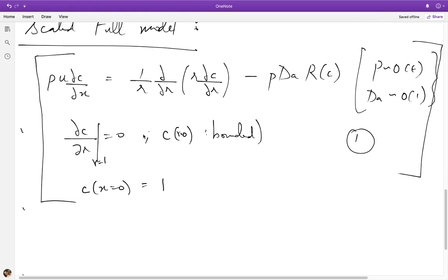Okay, so now we are in a position to apply the method of averaging by considering the case of small Peclet number, just as we had done for the case of laminar dispersion. There, instead of the reaction term, we had Peclet ∂C/∂T, which was grouped with the convection term. Now we have Peclet Damköhler number times the rate of reaction.